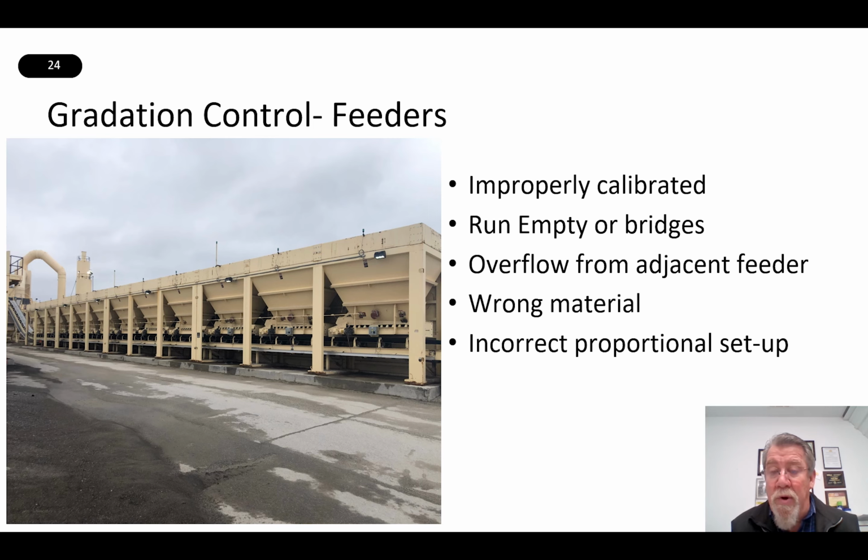The bridges could typically be your fine sands that have a lot of -200 material in them. They can bridge by sitting in a pile or sitting in your cold feed for 2-3 days. So make sure you have again your no flow sensors are working well, so it knows that the material is being fed out of the bins.